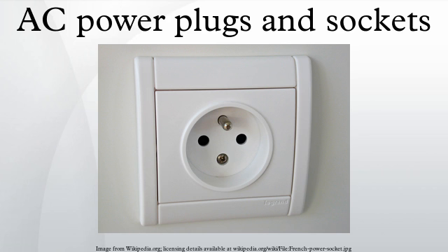Originally, sockets were rated at 10A 250V, because the NEC limited lighting circuits to 10A. In 1923, the code changed to allow lighting circuits to be fused at 15A, but the previous 10A rule still applied to circuits over 125V. The higher voltages were rarely used for lighting and appliances. Most sockets with this rating are of the T-slot type.